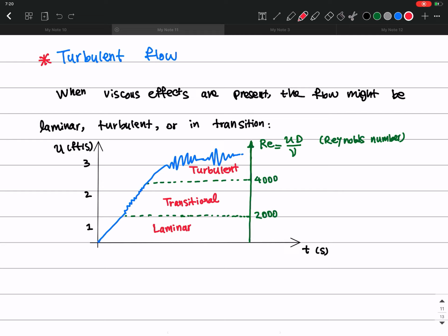So this was just a brief overview of what we learned and talked about, especially in terms of the fluctuations of the velocity which determine the turbulence of the flow. And just to note, again, turbulence is a very complicated problem. It doesn't have any analytical solution. So we typically use this kind of dimensional analysis framework like the Buckingham Pi Theorem to be able to get some relevant scalings in a turbulent flow.